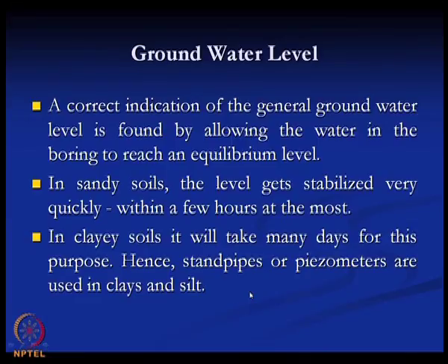So, the previous method is suitable for sandy soil, because it takes very little time, say a few hours. But if it is a clay soil or silty soil, then it takes a very long time, say many days. That is why that method is not suitable for clay, and in that case piezometers or standpipes are used to determine the location of the water table.